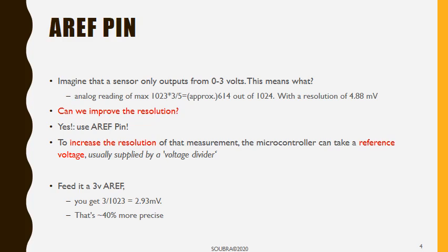Can anyone suggest another solution, without using the AREF pin, to have a better resolution? Someone from the other group suggested something extremely interesting. Anyone is able to do that here? No, without touching the voltages. Yeah. Forget it. So basically, there's another solution, which is to get a more sensitive sensor. However, if you want to do that, you'll pay more money for it. So it's more expensive, right? A more precise sensor. So instead of doing the resolution on the microcontroller side, you do it on the sensor side.